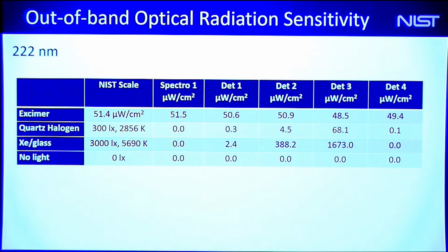This particular spectroradiometer measures pretty close to what I had over here. It doesn't have much of that stray light problem because it screens it out at lower power wavelengths. But with different detectors intended to measure 222 nanometer light, they're not all the same. So if you're going into a system to validate it, make sure the lights are off and it's at night if you want to get good measurements.